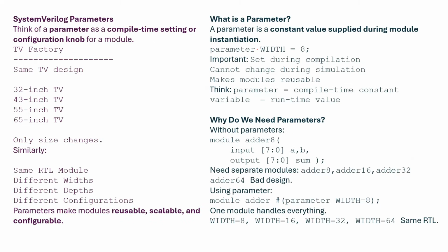Same way, the parameters we are utilizing here. Think of a parameter as a compile-time setting or configuration node for modules. Remember, this parameter never changes during runtime. Before runtime only, we fix some parameter, and only with that it is operating. Based on that only, it is creating the hardware, right?